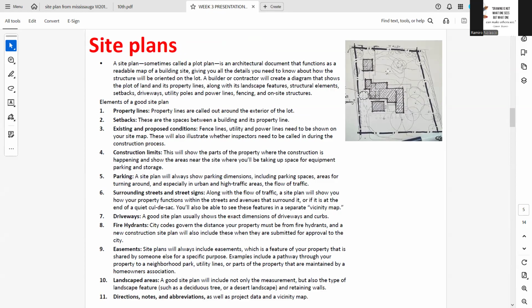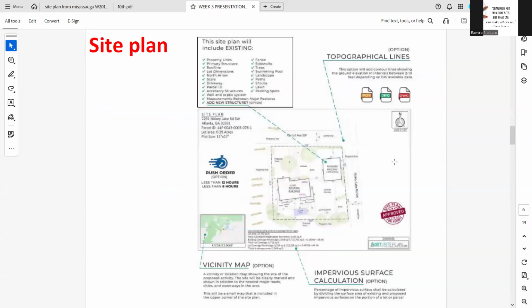Then you'll show the trees, shrubs, and the building footprint. You want to show the road and likewise the surveyor's annotation, the driveway and sidewalks, fire hydrant, anything that's important. You also want to show the direction of the north arrow, so that's when we show the true north and the project north.